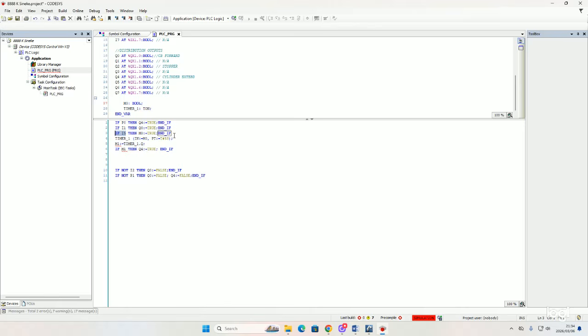So this is our output for our timer, this is the memory that has already been inserted in our input. If our I5 memorizes this memory latch, which is M0, then our Q4 cannot be true because our Q4 is advancing a cylinder, but now the timer is not for advancing the cylinder but for retracting. So then we need to insert false. Why? We are retracting, and our Q4 is for advancing. Okay, right, so we end if.